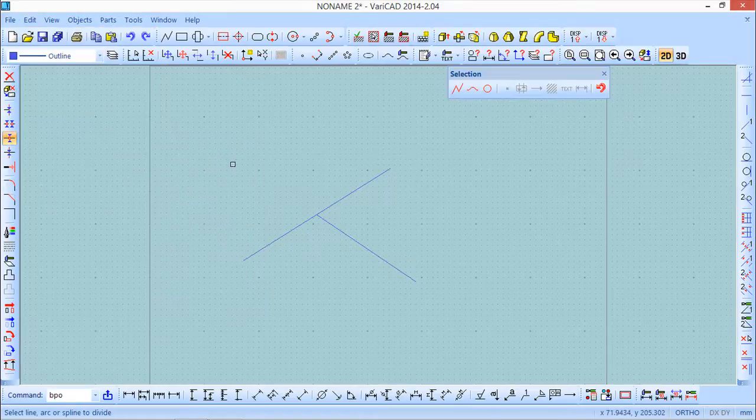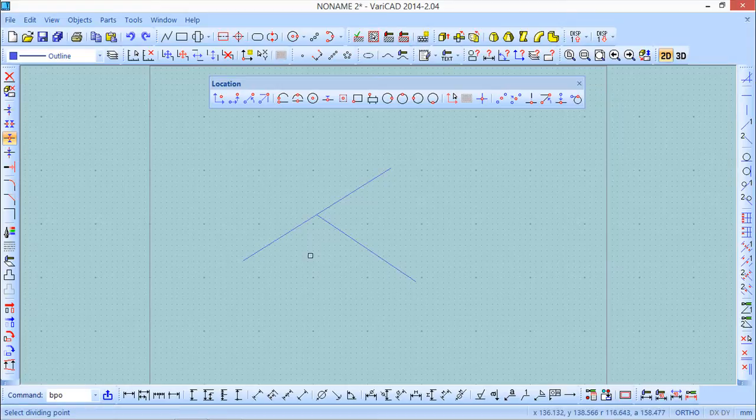divide by point. Basically, if I create a line here, this is a single entity, but I can split this entity in two or more, though I can make one split each time I come here. And this split is done by a selected point. So in this case, first I select the line, then I select the point. Just to be easier, I could use any point of the line or intersection or wherever.